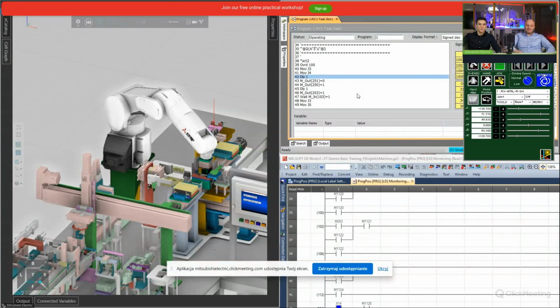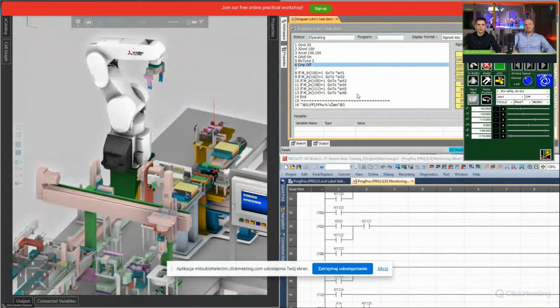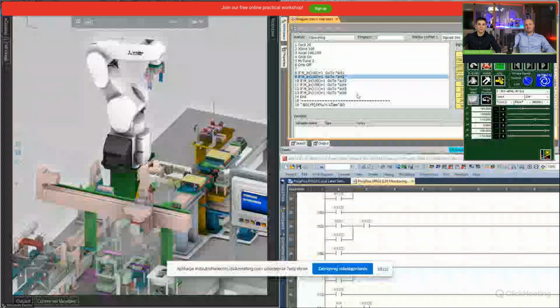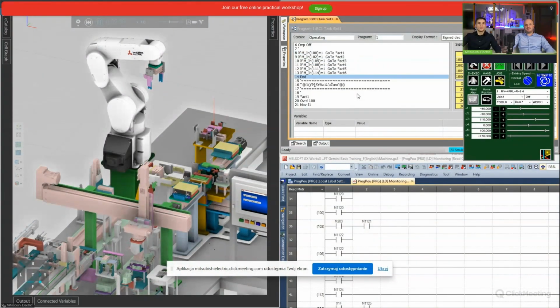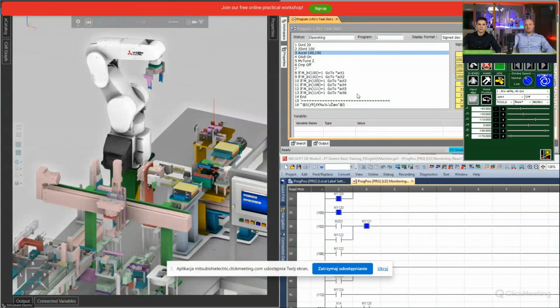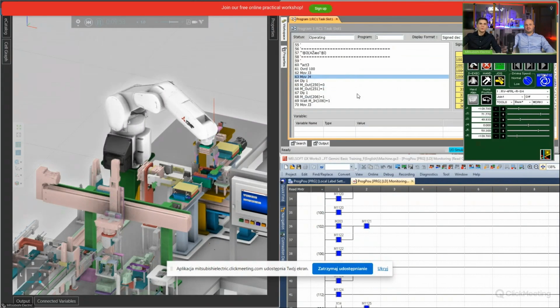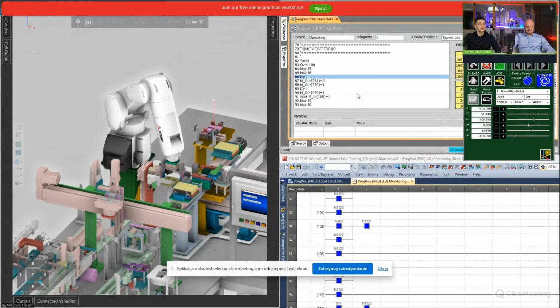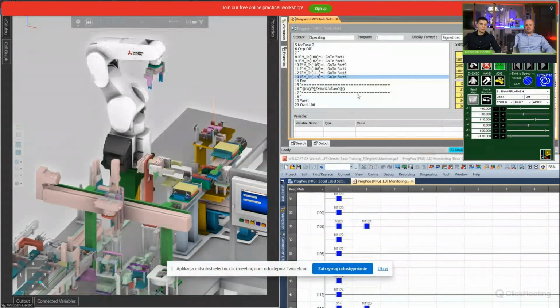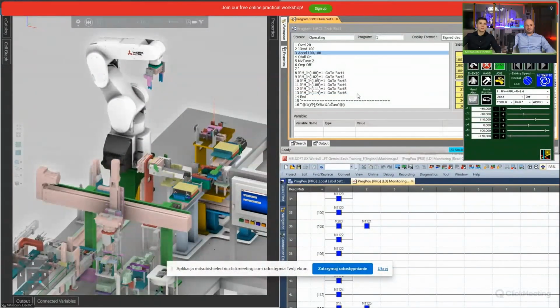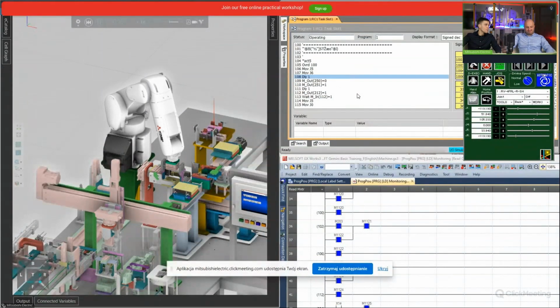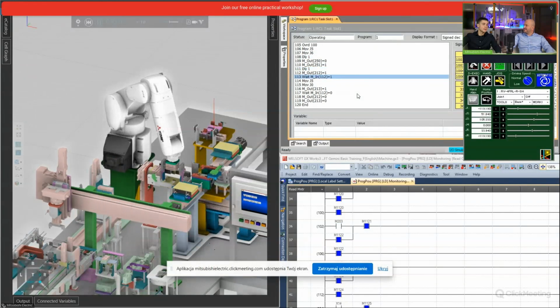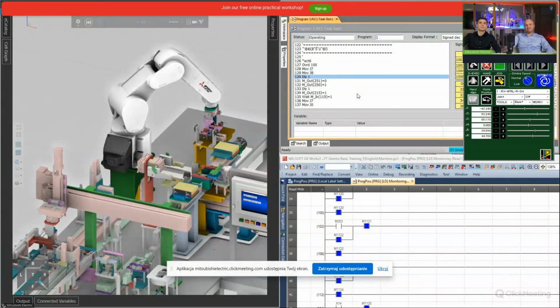Yes, and the robot simulator calculates the dynamics of the robot based on the mass and inertia of the load. So we can measure cycle time there. And when it comes to a manipulator, we have acceleration time, deceleration time, and speed in the servo controller. So to sum up, we can measure the cycle time of the whole machine.